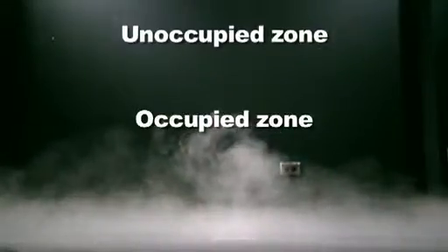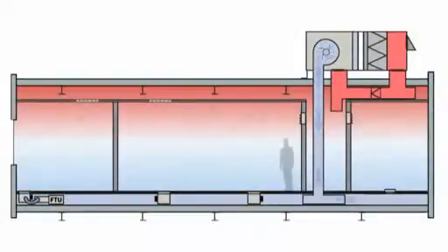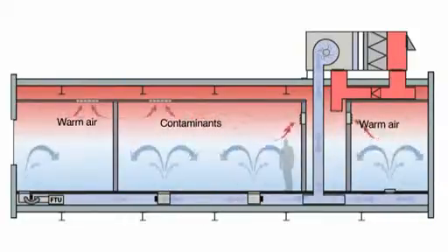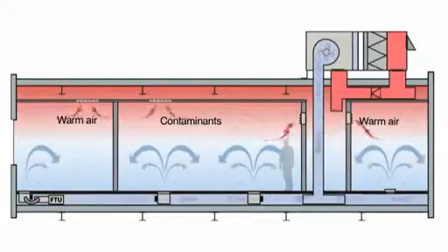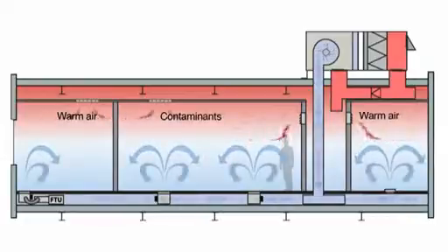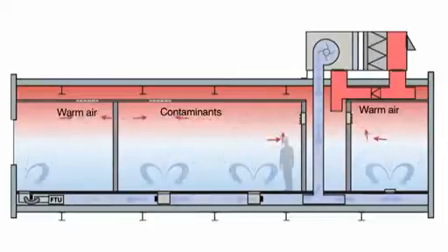Above this point, the warmer air will rise out of the occupied zone into the unoccupied zone, where the heat and contaminants are allowed to stratify. There is still some mixing in underfloor air systems, in the first 4 or 5 feet above the floor, but not as much as overhead systems. Most of the warmed air and contaminants stratify high in the space, carried there by plumes of heat from all heat-generating sources in the space. Underfloor air distribution puts the conditioned air in the occupied space in the first 6 or 7 feet where it is needed, where the people are.